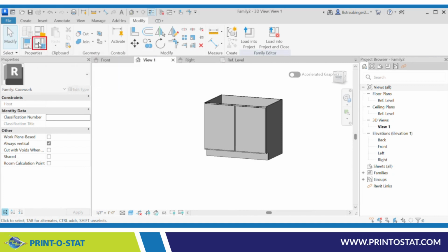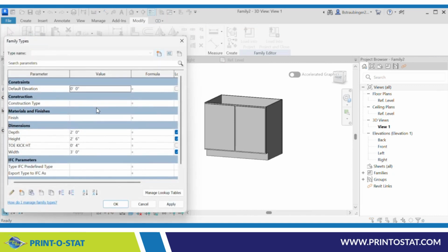And now I'm going to show you the power of this family types box. This is very cool. The height, I really want 2 foot 10.5 because your countertop's usually 1.5 inches thick. The width is fine. Toe kick's fine. The depth is fine. I'll hit apply. And now what I'm going to do is rename the type.